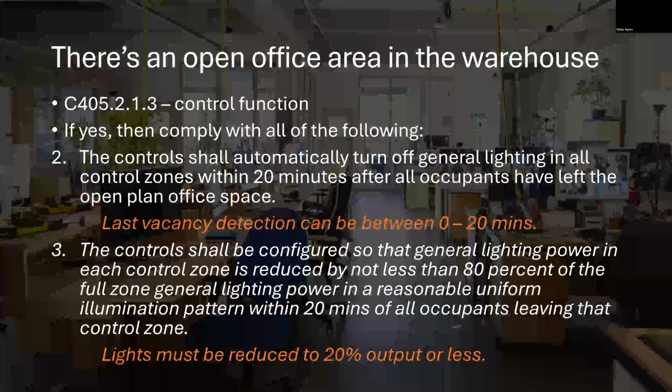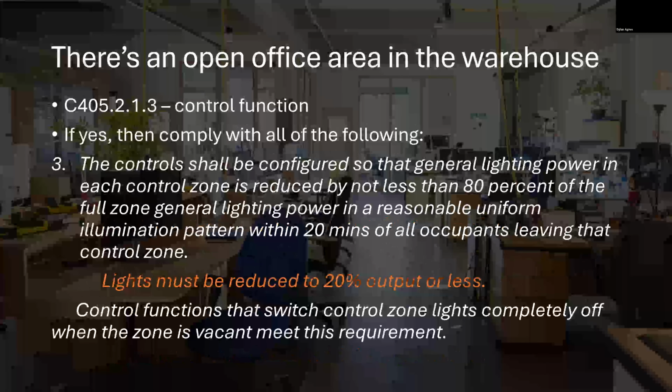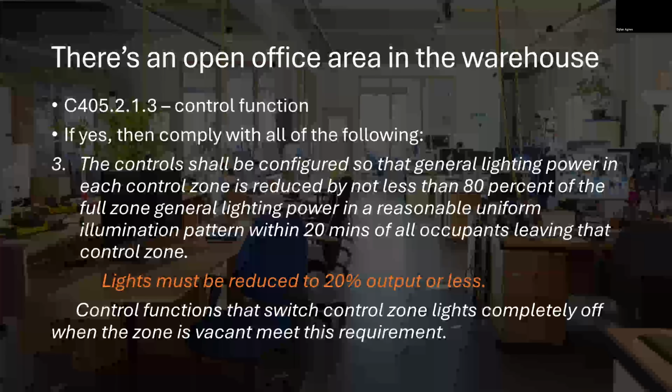And then lights must be reduced to 20% output or less. The control shall be configured so that general lighting power in each zone is reduced by not less than 80%. Code really writes it this way because it has to be an absolute, but I like to rewrite it. Basically, lights must be reduced to 20% output or less. Control functions that switch control zones' lights completely off when the zone is vacant meet this requirement. So if you just want to say, hey, we're not going to dim to a certain threshold, it's just going to go to full off, you're good to go.